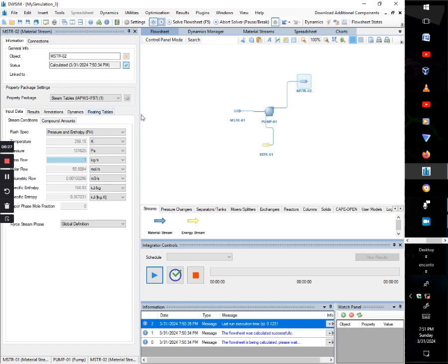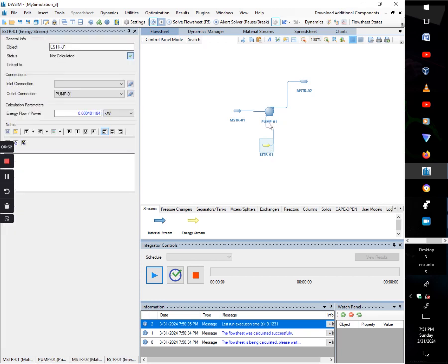So I want to give you an assignment. I want you to try and calculate from your energy balances the energy that will be supplied to the pump using the mechanical energy balance equation, and try to solve for a pump efficiency of 75%. Try to find the energy input that will be required by the pump. If I take my stream 2, the energy flow in should be about 0.000400184 kilowatts.